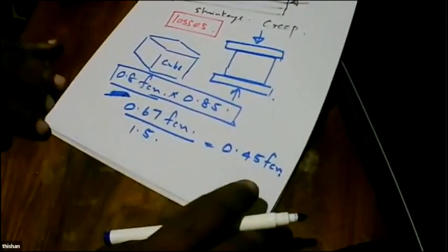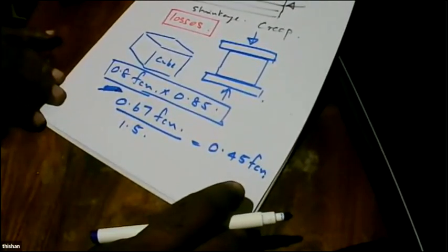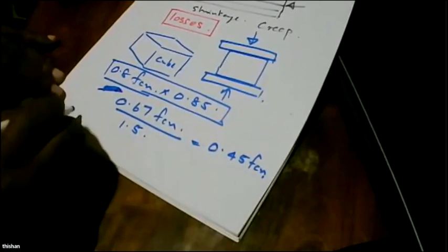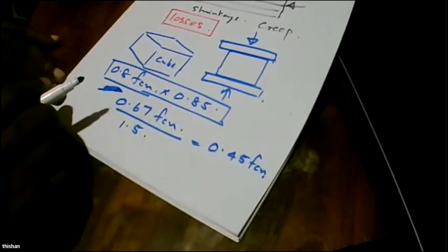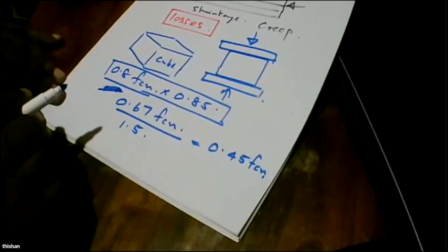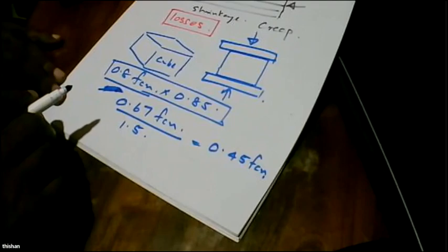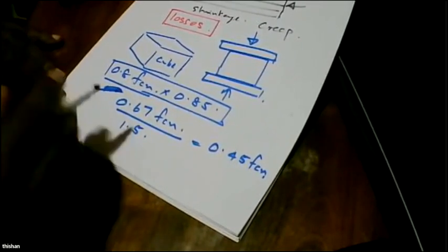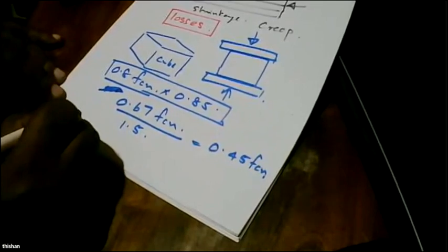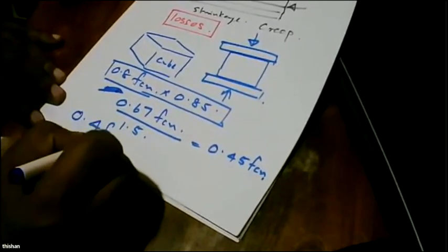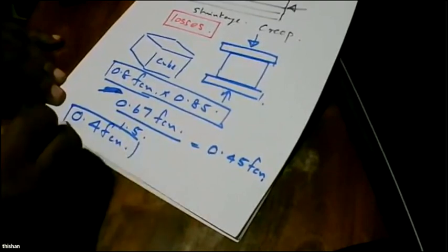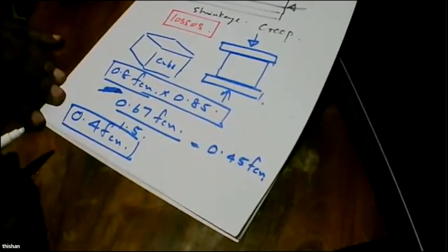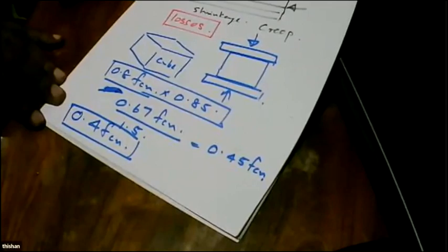So for bridge construction, which has a special type of stressors, because when it is subjected to only the self weight, we get some load, and then we design the bridge for a very high load. So because of that reason, the allowable stress under British standards was considered as 0.4 times FCU.